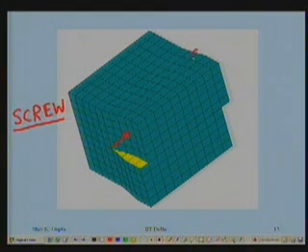I wrote G on this point and H on this side. So my T vector is from H to G. That's my T vector. With this T vector, which way should my Burgers circuit be drawn, clockwise or anti-clockwise, so that the right-hand screw rotation moves inwards? Clockwise. So let us start in this plane at this point P.